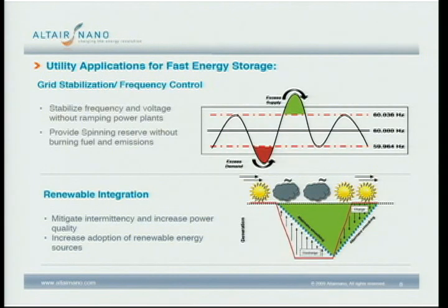In this example, this is the utility system controlling the battery system. Utilities looking at their system saying, hey, my frequency is too high, my frequency is too low. Typically, they'll send a signal to a generator: I need more power, I need less power on a 4-second basis. They're going to control the battery the exact same way. It's actually a communication control, but they're going to switch it on and off, and they'll tell you how much to provide.